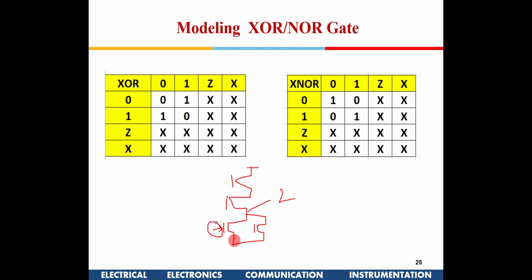Like for example, for a TTL gate family, open actually indicates 1, right? Okay. For CMOS logic, open is 0. So for various circuits, Z may appear at the input as 0 or 1, okay?